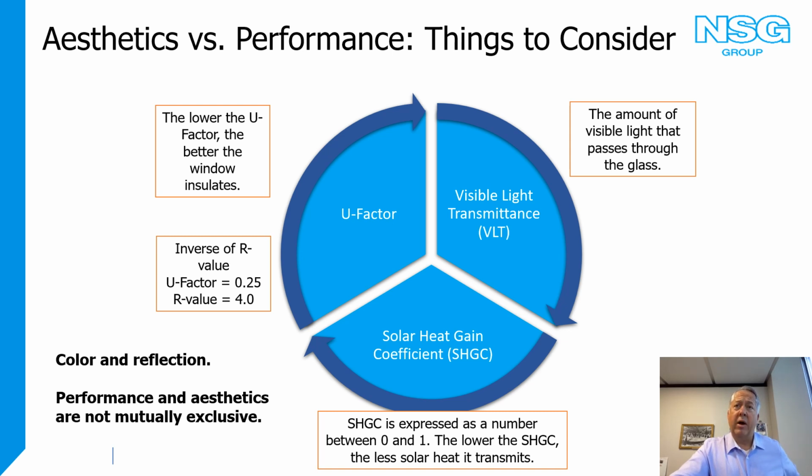There's lots of things that we talk to people about when they're designing windows and buildings, but the three primary performance factors are U factor, SHGC, and visible daylight. SHGC and visible daylight are pretty similar. SHGC is, of the sun's energy, between a ratio of 0 to 1, how much of that gets transmitted through. Same thing with the visible light, how much of the daylight gets transmitted through. So a 1 would mean 100% of it gets through, and a 0 means it blocks all the sun's energy. In addition, you're talking about U factor. U factor, the inverse, is R value. So the lower the U factor, the better the insulator that is. When it comes to wall insulation and things like that, people tend to talk about R value. A higher R value is a better insulator. So it's those three characteristics.